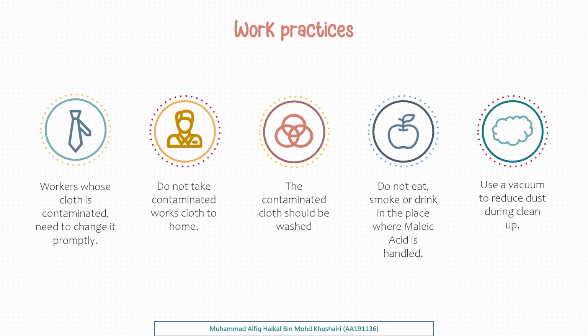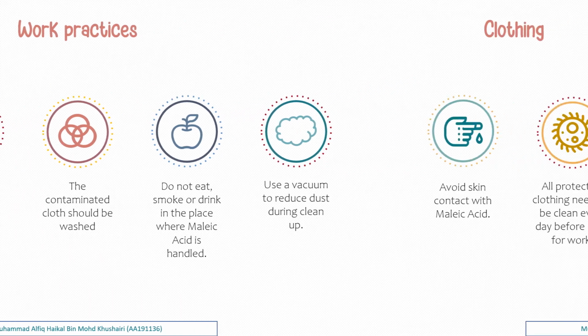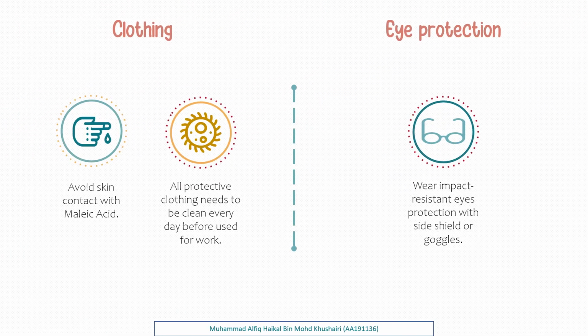Use a vacuum to reduce dust during cleanup. For clothing, avoid skin contact with maleic acid: wear resistant gloves and clothing. All protective clothes need to be cleaned every day before use for work. For eye protection, wear impact eye protection with side shields or goggles.